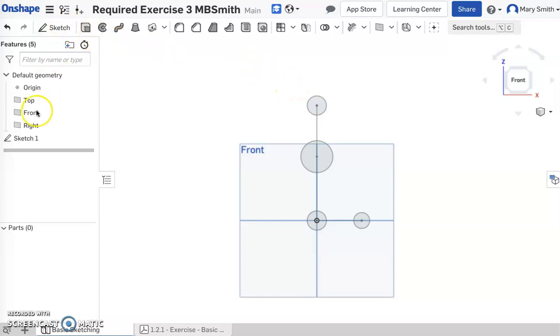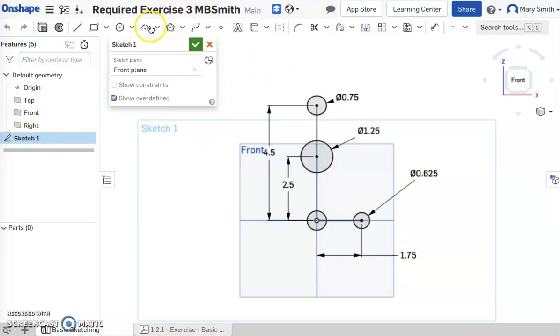Here you want to be really careful. I go back to sketch 1 to grab the line tool and make each line coincident with the circle, but nothing else. Notice how if I make a line that's close to horizontal, see that little line there that pops up next to it? It says, if you click now, I'll make you a horizontal line. I wouldn't want it to be horizontal. I'm going to make this line also coincident with this other circle, but nothing else. You'll start to see things like that. That's a tangent constraint. We don't want that to happen yet.